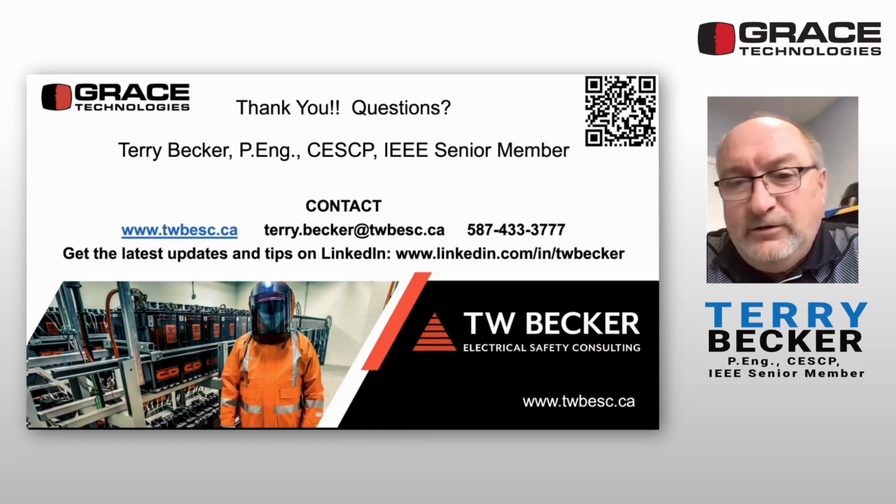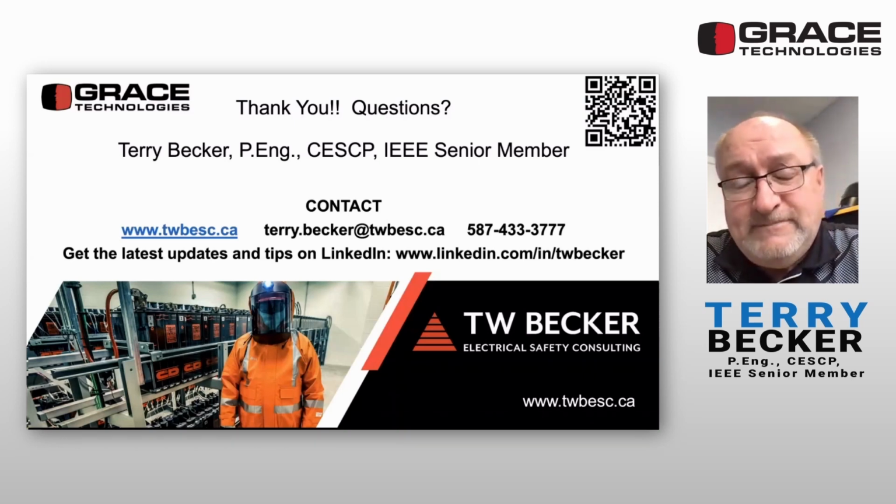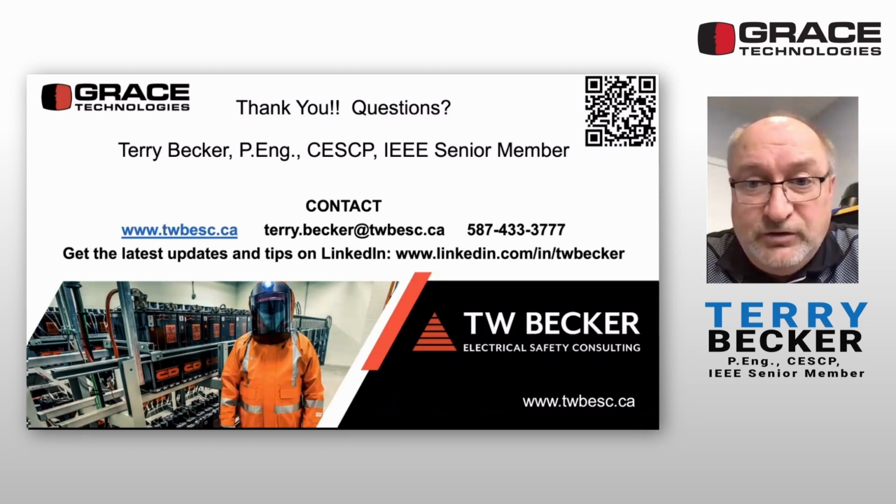Just look at commercially available everyday task wear, coverall, shirt or pant, and get the ATPVs between 8 and 12, and then go to an arc flash suit. But I encourage you to buy arc flash suits with a higher ATPV, 75, 100, 140 cals, and get rid of the 40 cal myth. And yes, balance substitution and engineering safety by design and attempt to lower incident energy, but balance the cost and technical feasibility to do so with arc flash PPE, right? Because again, these arc flash suits, when you do a qualitative risk assessment, do reduce the potential severity of injury damage to health residually to 50%, probably secondary burn injury.